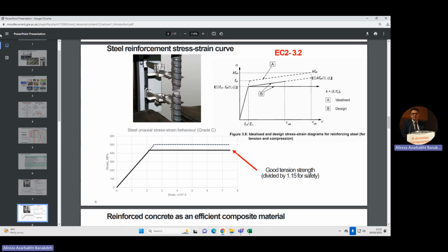We are doing the same thing for steel, okay? This is the reinforcement. In the lab, we are just applying tension to make it crash. And the behavior of steel is like this. It's quite more predictable than concrete. This is epsilon, and this is sigma. This is strain. This is stress. This is, again, steel in terms of percent. You remember we were working about 3.5 here for concrete, but the steel goes to 7 something. It goes farther than concrete.